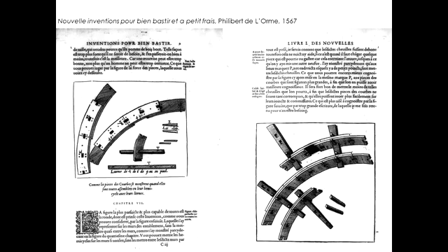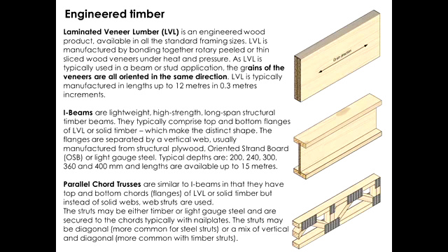And the overall idea was to make an arch with a very long piece of timber that could be considered nowadays as a composite product. But that was really just the beginning to develop what we now know as, for instance, LVL, or the I-beams, which are made of two different elements. So, for instance, the top chord and the bottom chord are made of LVL, and OSB is used to do the web.